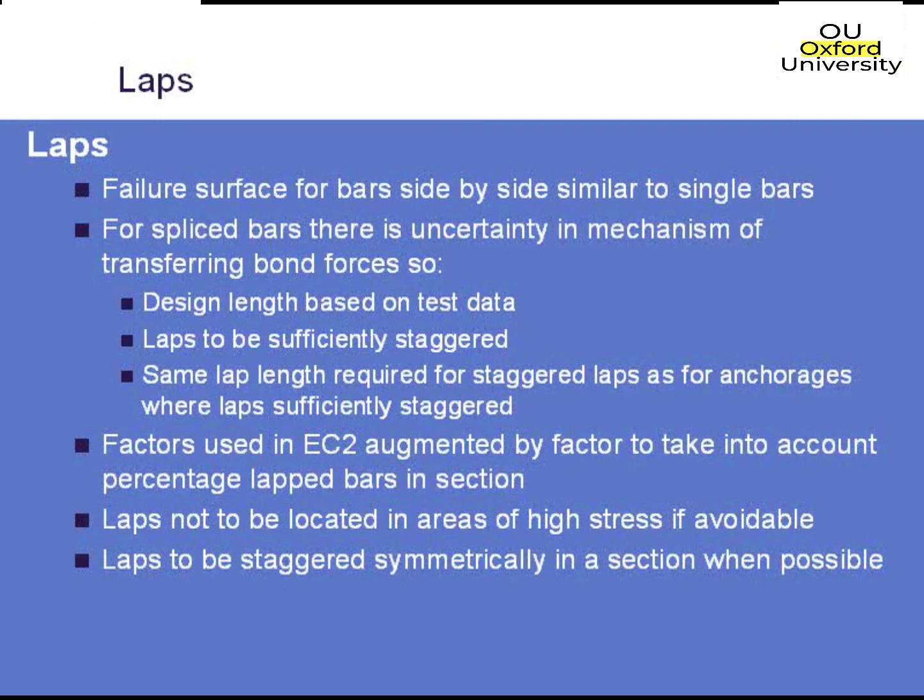So the general practice behind laps is not really that different. And same as before, you're not locating laps in areas where you've got really high stresses. Again, if you've got a pile to abutment connection, that might be difficult because the connection usually is in a very high moment zone, so it's hard to avoid. But if you've got a deck, you probably put the lap at the point of contraflexion rather than at the biggest bending moment. So it's pretty much just stating good practice on that slide.